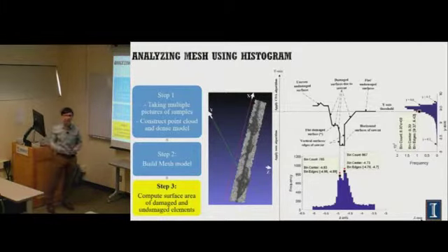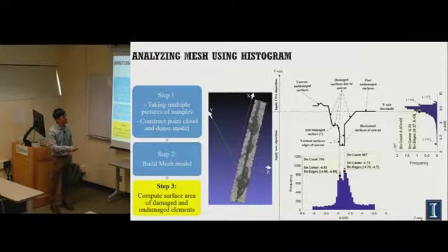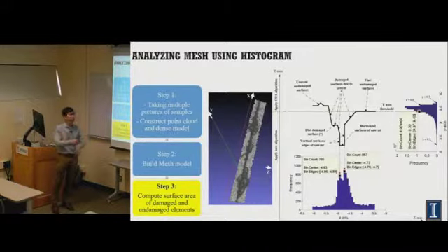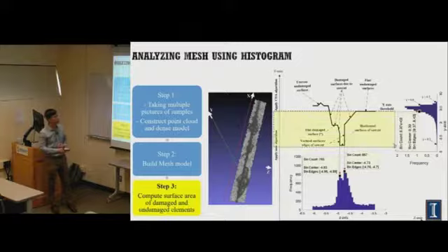It's not the spalling damage. It's just the saw. So I need to eliminate this area first by using the z-axis histogram. These 2 peaks will tell me where the groove is, the 2 sides. And this histogram will tell me where the damage will be, right? Because the surface here will tell you, okay, most of the flat surface will be the peak. So that's the first technique I use to detect the damage below the surface.